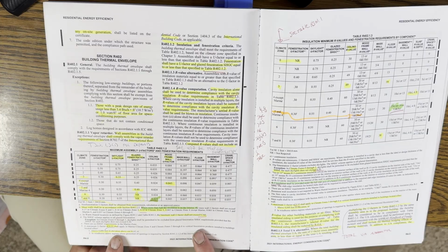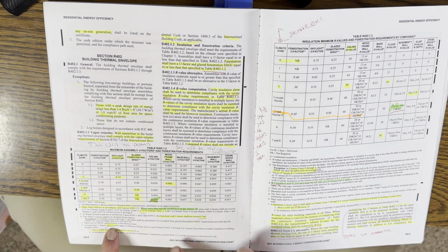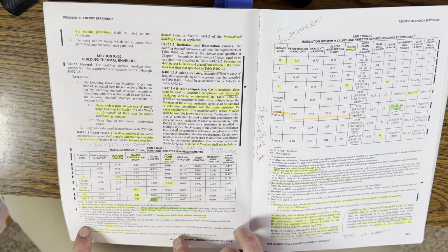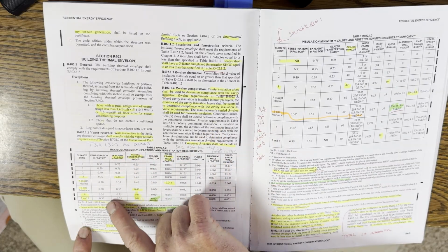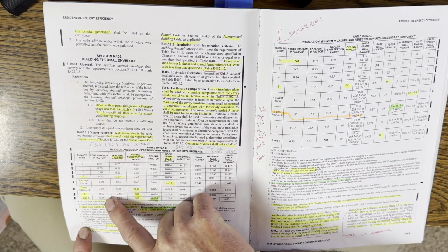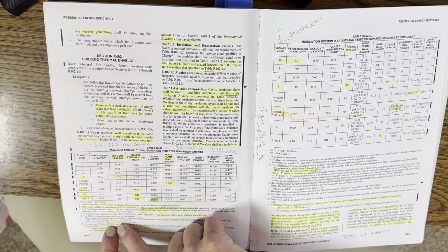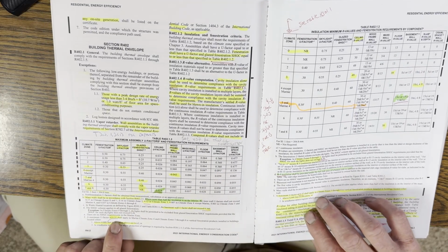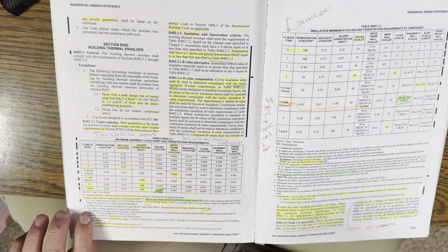Did get a question about this. This is another Summit County, Colorado question. The question was maximum U factor, footnote F. So footnote F, fenestration U factor, I think it was climate zone 7. The number is actually 0.32. It's not 0.3, it's 0.32. So, they're trying to throw you a little bit, and that's because it's above 4,000 feet. You got to look at that footnote.